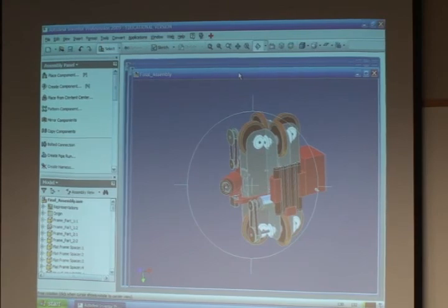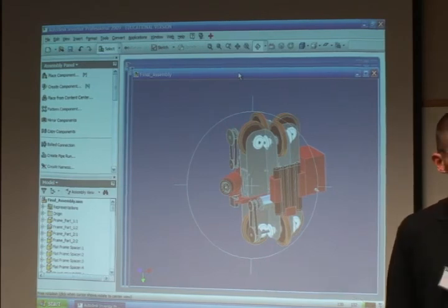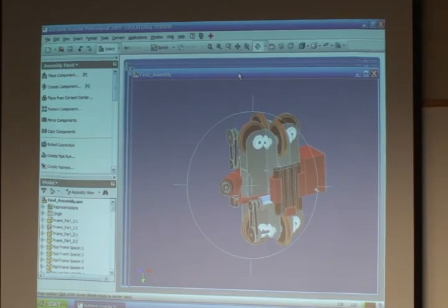Just those little things like that will cost you a match. Those little pieces of information are the key ones that you really got to look for. Anytime you can use a Torx head versus a socket head, or what we refer to as an Allen head, it's a lot easier, with less chance of stripping. When you go into a competition, have your wrenches identified. If it's a T15, T20, T25, color code them so that there's no mixing up and stripping out the head. Allen heads are a lot tougher to use, but sometimes you have to use them, like Rick said.